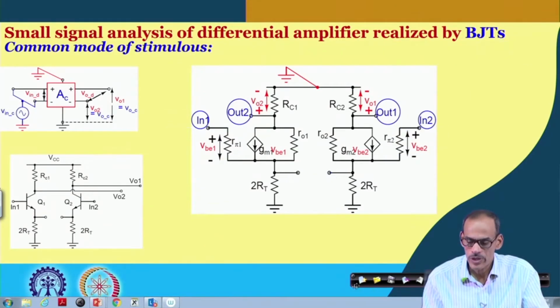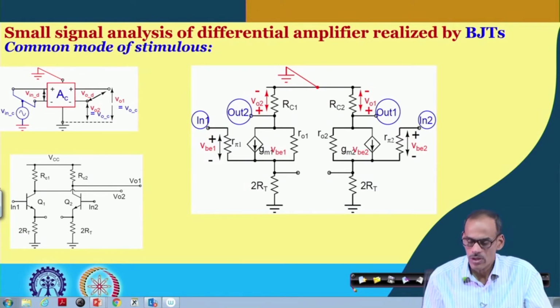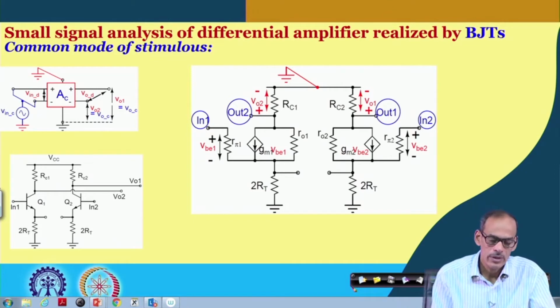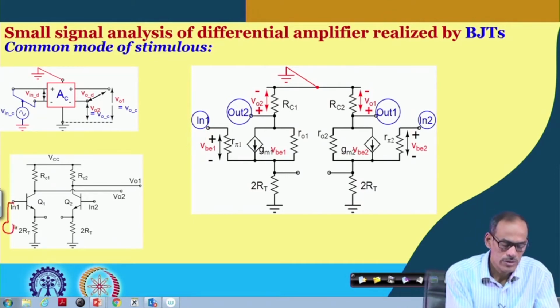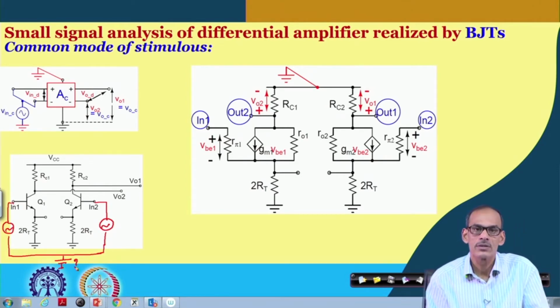Now, so far we are talking about the small signal situation. You may recall that while we are applying the signal at the input, we are also applying a meaningful DC. So, the next question is what may be the meaningful DC, that can be analyzed by considering large signal behavior of this entire circuit.